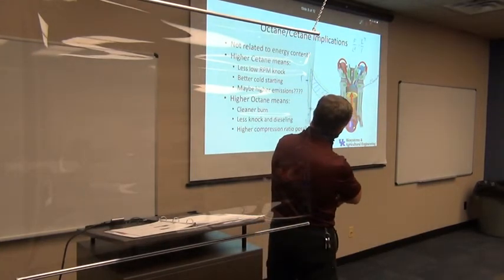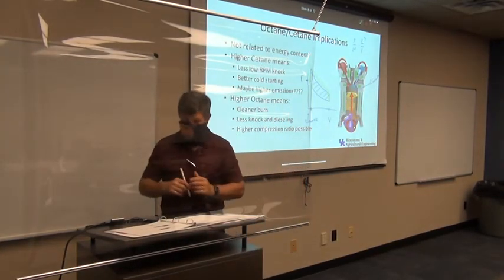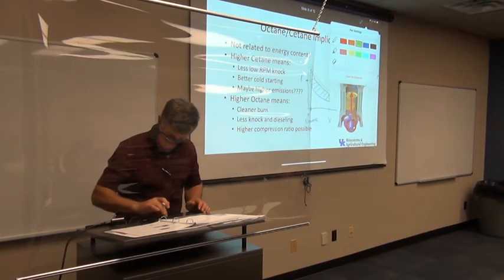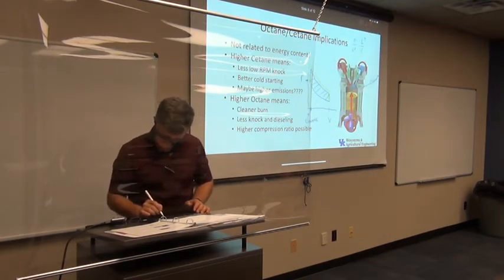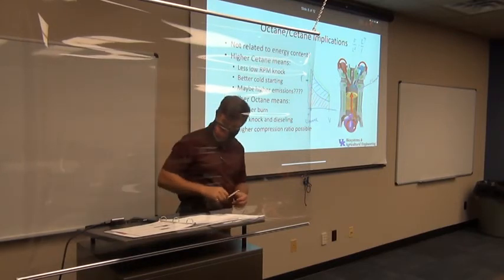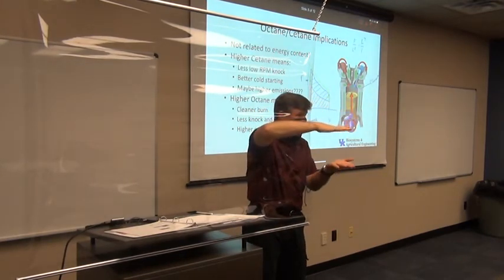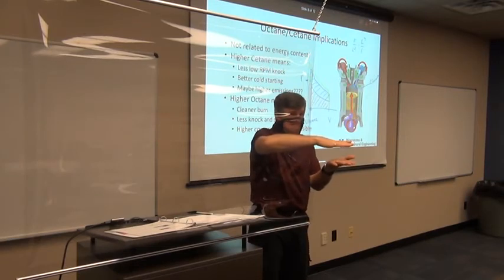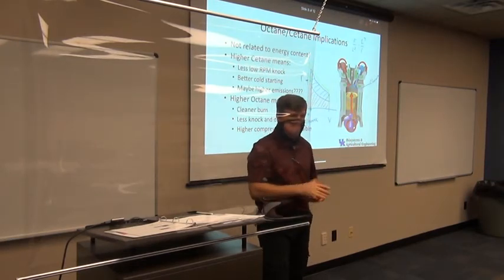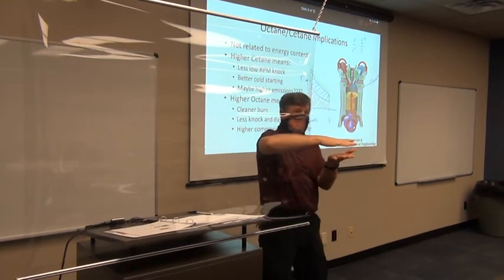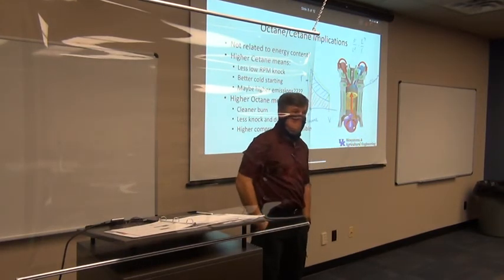What do you think? Got any idea? Isn't that what's below the curve? Absolutely. Exactly what it is. It's what's below the curve. So when we draw red, this is my energy loss. If this pressure does not get down to zero, it's all of this underneath that curve. That's the energy loss. It's essentially the energy that I have to put into that fuel air mixture to compress it. That's fundamentally what it is, in addition to friction and some other things. But in the thermodynamic cycle, it's the energy that I have to put into compressing that fuel. That's energy that I can't recover, that I can't get back.